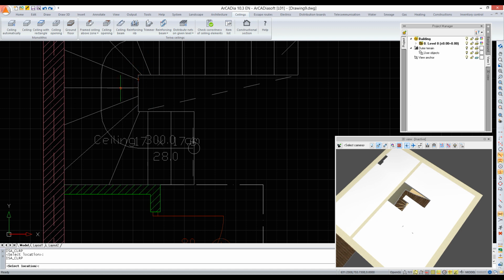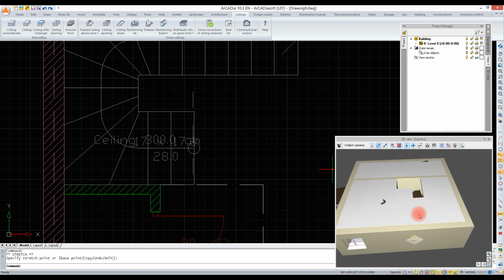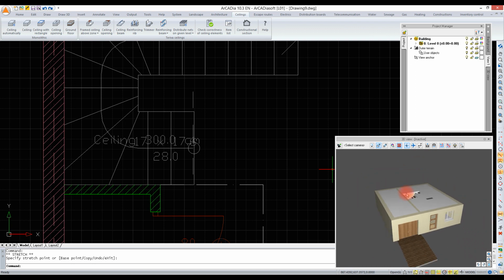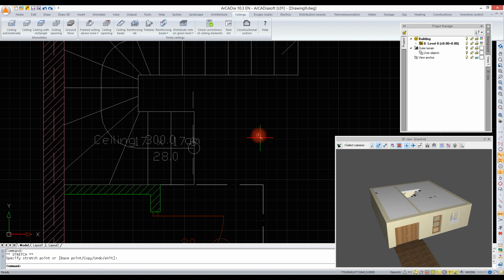If the shape of this opening does not correspond to our needs, we can modify it. After selecting it, in the Edit window and the Delete Point option, we indicate those points that we do not need. We finish with the right mouse button. We select the opening again and we move one of the nodes. And this is how the modified opening looks.